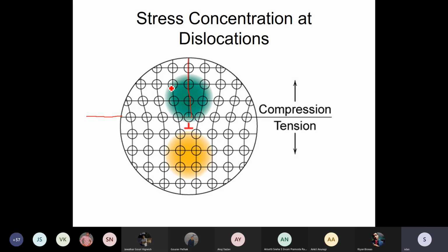But to maintain the continuity of the geometry of that solid, the solid applies a force or stress towards this extra half plane. What type of stress is this? Compressive. Yes, it is a compressive stress, because this extra half plane is trying to bulge the solid crystal outwards to maintain the geometrical integrity of that solid, no change in shape. A compressive stress is applied on that.